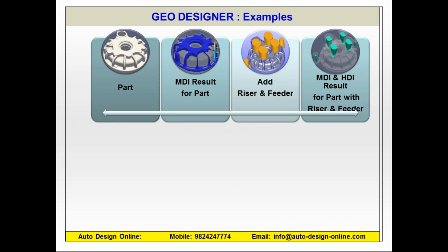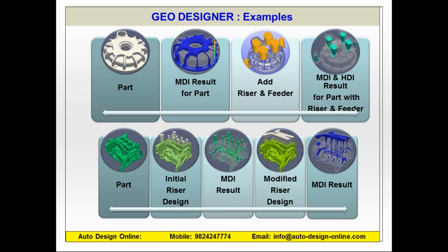Now, what other example can we see here? These are even complex parts or large parts like an engine block. If the risers are provided in this engine block, you can see the riser will dry very quickly. So how can we provide further metal to the riser so we can ensure that it will keep feeding these sections inside the engine block? Now you can see that if you provide such a kind of top side, it will keep feeding this material to the engine block, and that's how you can optimize the requirement of your riser, or the runner or the feeder and so forth. So this could be useful for different types of casting parts irrespective of your process.